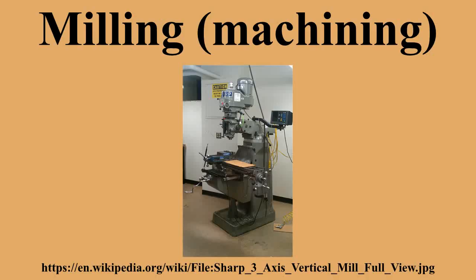A turret mill has a stationary spindle and the table is moved both perpendicular and parallel to the spindle axis to accomplish cutting. The most common example of this type is the Bridgeport, described below. Turret mills often have a quill which allows the milling cutter to be raised and lowered in a manner similar to a drill press. This type of machine provides two methods of cutting in the vertical direction, by raising or lowering the quill, and by moving the knee.